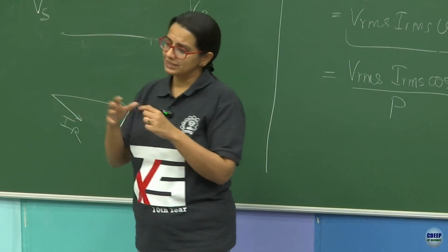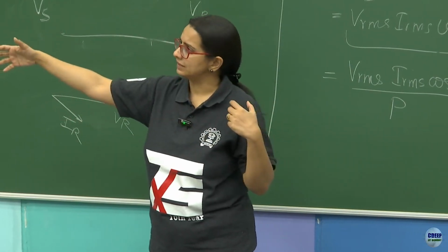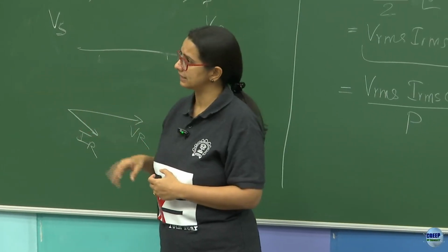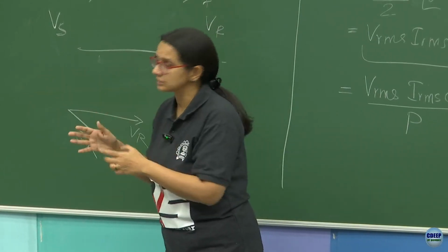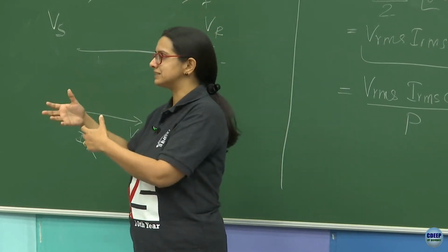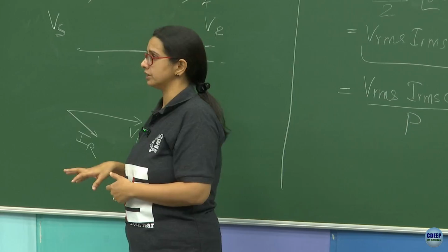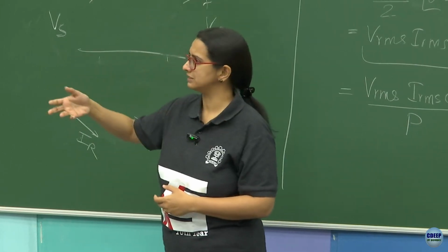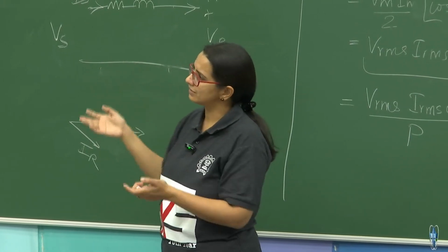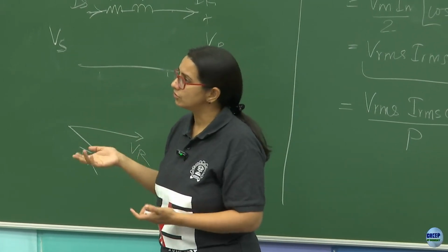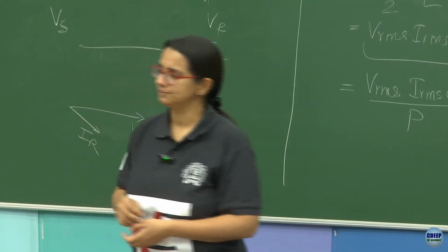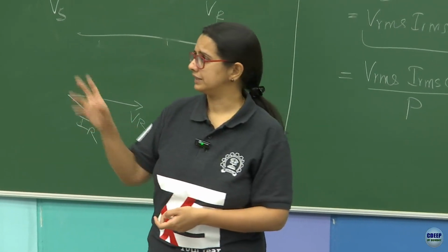But when it's a long enough transmission line, you start seeing some effects of this capacitance, weak as its dielectric may be. If it's a short transmission line, which is what I'm focusing on here, you would not have too much capacitance effect, so you can in fact ignore it. The capacitance is so small that the associated impedance is very large. It's almost like an open circuit, so you ignore it. That answers your question.